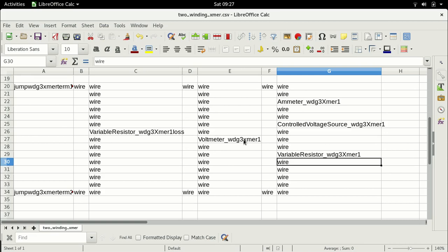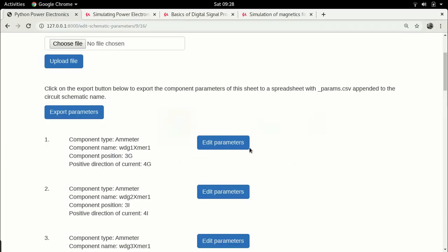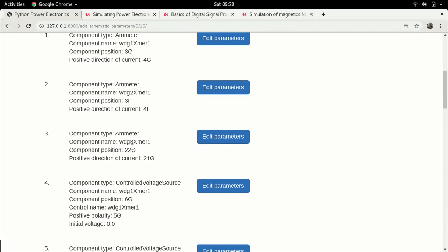That will come next. So therefore, we need to adjust all these polarities to face downwards. So ammeter, of course, will be upwards, but all the other polarities will be downwards, because remember, whichever is the dot polarity, the current enters that polarity, right? And all the other voltages have a positive polarity towards the dot. So let's make that change. So winding, this will need to change.